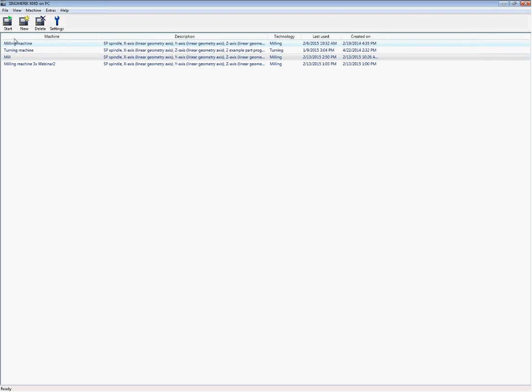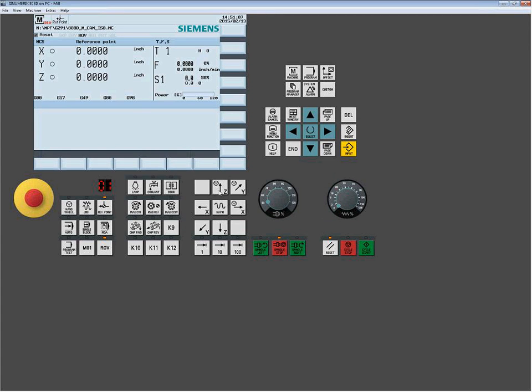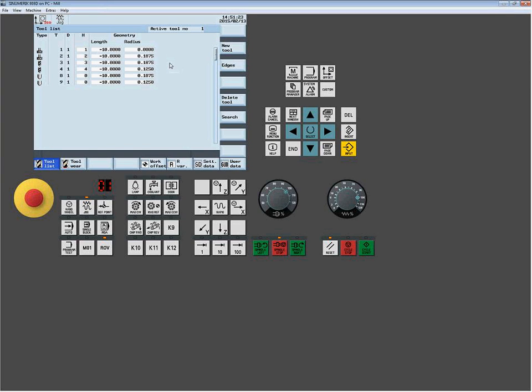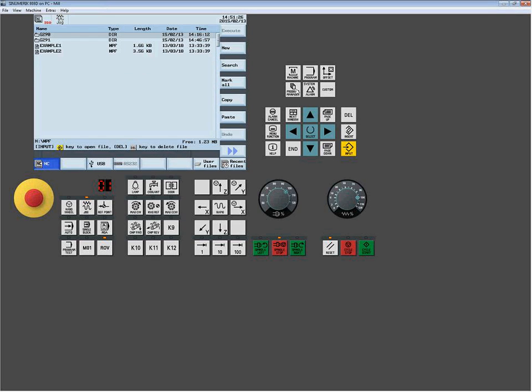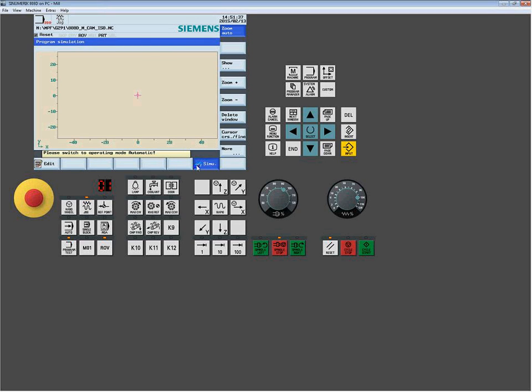I do not have the ability of doing that radius trick that I was showing you before for the Siemens side. Those upper level instructions or functions are certainly things that are reserved for when running in Siemens mode. So that and a lot of other commands, as you start to get more in depth in the control, you start to lose when you're in ISO mode. So just be aware that you are going to compromise or give up some functionality or features when running within this mode. So let's jump back in. I want to just resimulate that for you. Excuse me for having to reset the machine. It's a PC. Gotta love it.